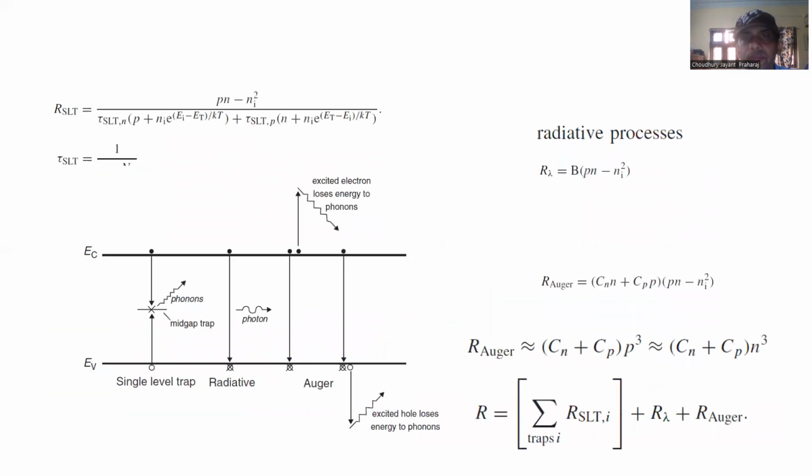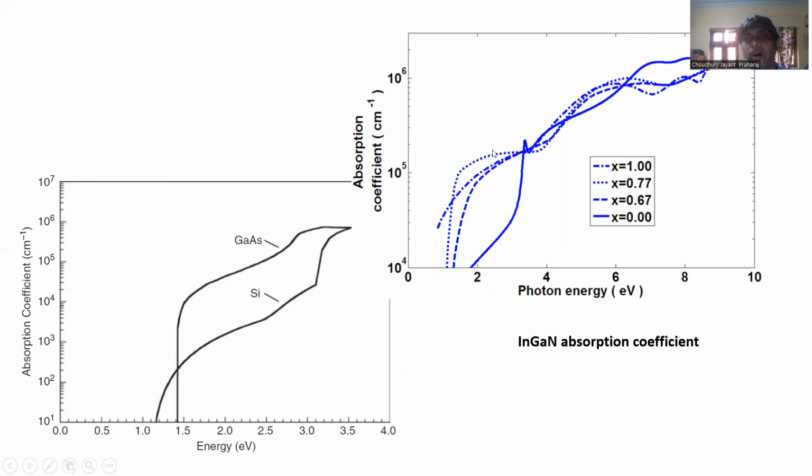Okay, a little bit more about this. I'm staying on this slide just because it shows four different indium concentrations, and that is relevant because as we go to higher gallium concentrations... this is a slide about absorption coefficient, but I'm talking about a slightly different topic, and that is the electron and hole concentrations that can be obtained by impurity doping or shallow donors and shallow acceptors, and the kind of contacts that can be made for these materials.